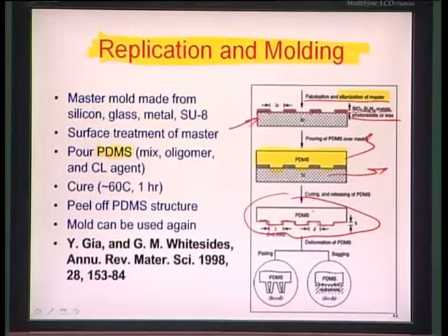And one more issue here is the aspect ratio, which needs to be carefully and precisely done while designing. As you know, PDMS itself being a soft material, there is always a tendency of these extra arms or long arms to pair up or sag down, as you can see here. So the aspect ratio of design is very critical. The sagging down would happen due to overweight, particularly when the posts to support the whole structure are very small and they are spaced by a large distance, whereas this adhesion mechanism between the two projected pieces would work out when the material is too long in comparison to the distance of separation. So they are like filaments coming out, and they tend to adhere to each other by local van der Waals forces of attraction.